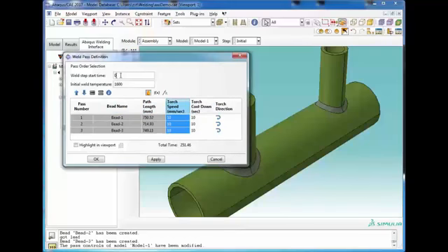Now there are 2 items up here, the weld start time, if you want to have a delay. In this case, we're putting a big weld down and a small weld, so we could put delays in when one of the welds starts. By putting in 0, it just says it's going to start immediately at the beginning of that step. And then the initial weld temperature, which you'll notice looks like the stress cutoff temperature, is the initial temperature at which a weld is inserted. When we activate a weld element, it's presumed to be activated at or near melt temperature. So the default is this 1600, the stress cutoff temperature.